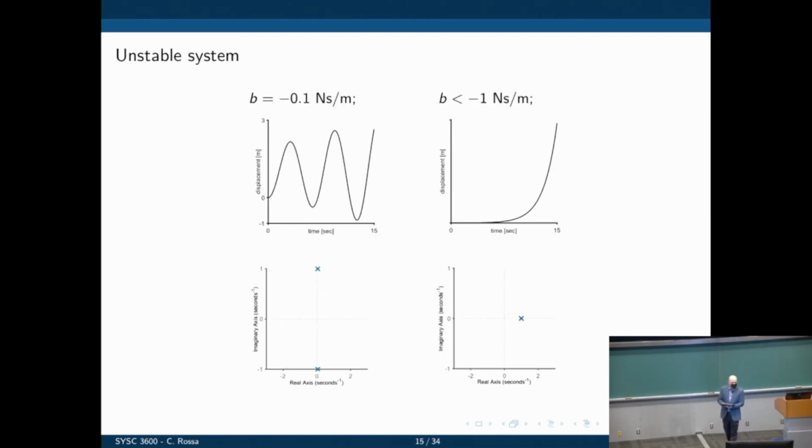Here is the result of that. We see now that when zeta is negative, we still have complex poles for this example, but now the real part is positive. We enter the unstable zone. We are on the right side of the S-plane. The exponential goes to infinity and brings the sinusoidal with it to infinity. If you keep decreasing the damping ratio, the poles may go back to the real axis, only real, but now they are positive, and then the exponential grows to infinity, and the system is unstable, same as the case for the first order system we saw in the last lecture.